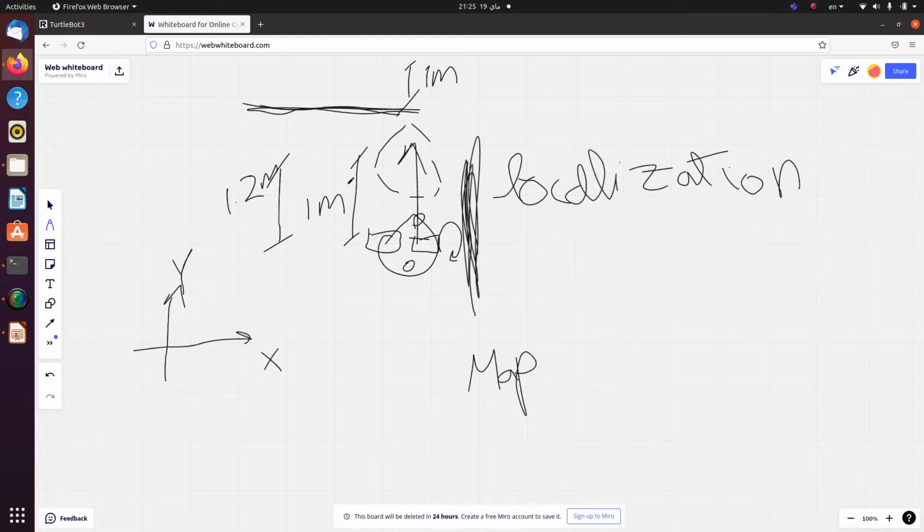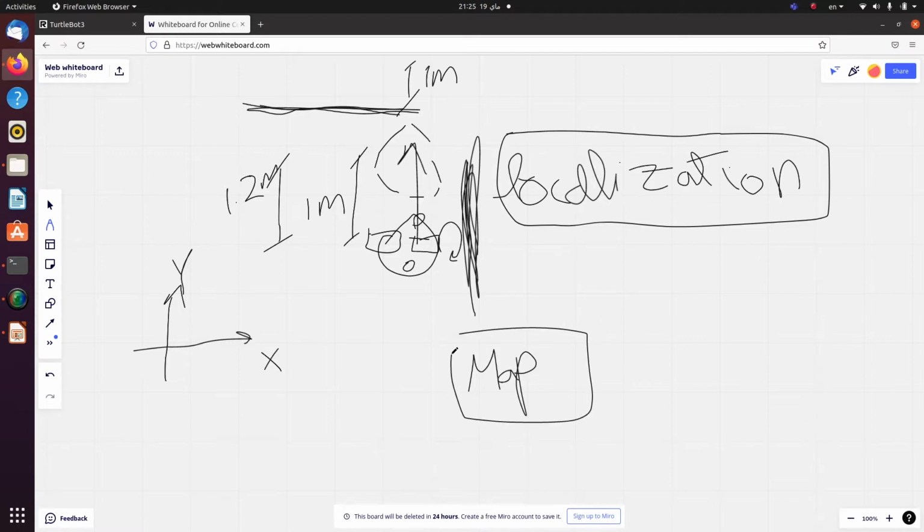So what the localization process includes is that we compare, for example, the readings from all sensors against each other, and we compare them with the map readings. We have the map, which is the source, and sometimes we have something called a prediction. What this prediction means is practically any dead reckoning source.